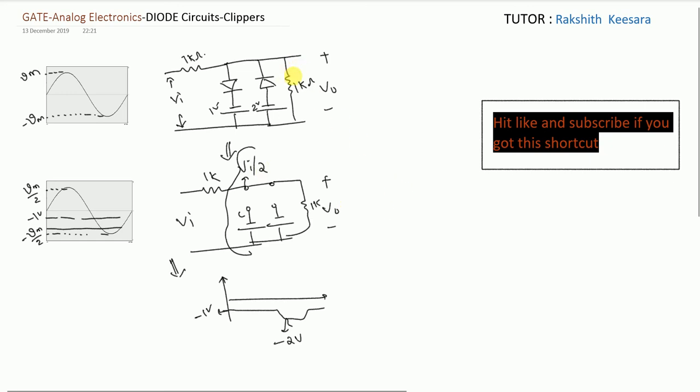Why? See, assume guys, if this resistor is not there, whenever the diode is open circuited, this is our equivalent circuit, right? So direct Vi will appear here and we are comparing directly with Vi. But whenever there is a resistor, it is not the voltage Vi appearing. Vi by 2 is appearing here. So we are comparing with the Vi by 2. It's as simple as that, guys.